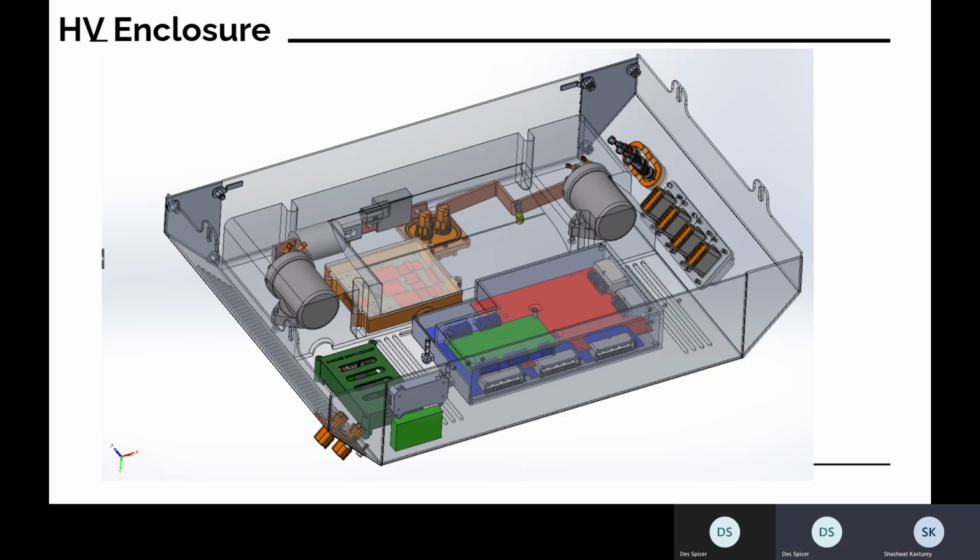So this system has since been redesigned. I believe what we're using now is 2 DC-DCs on a plug board. We've also broken out 12-volt power inside of this because all of these boards run off 12-volt power. A lot of stuff has been removed over the last 6 months, so don't take this as gospel. That's correct. It has 2 modules on it. One transfers from 400 volts down to 24 volts, and the other transfers from 24 volts to 12 volts.